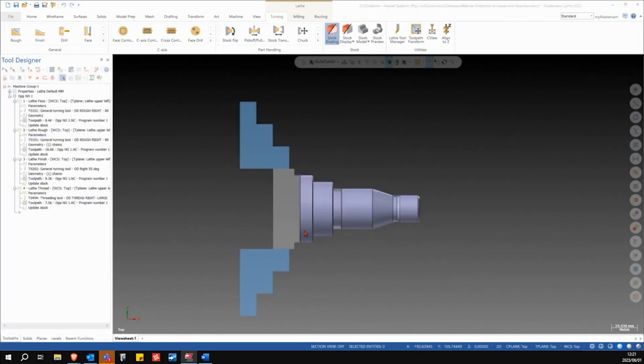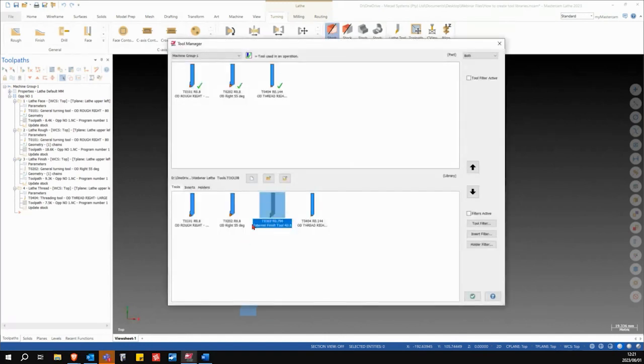And then we green check. Mastercam will tell you library updated successfully. So you say OK. And there you see your 3D tool in your library that you've created, your custom library. And now I want to use that in my file. So I'm going to click on it and drag it to the top in my part file.